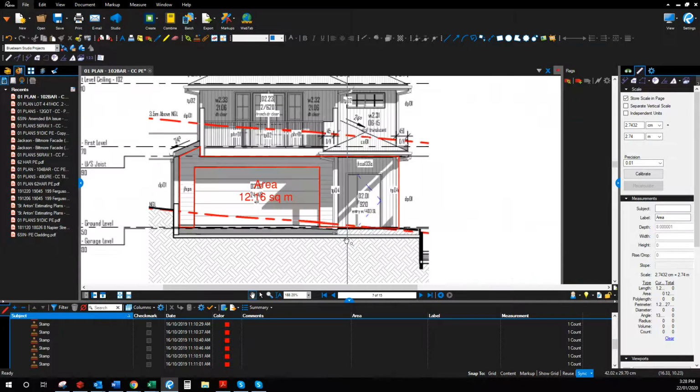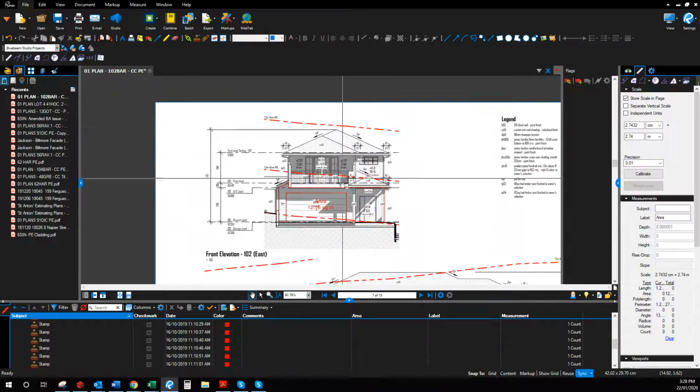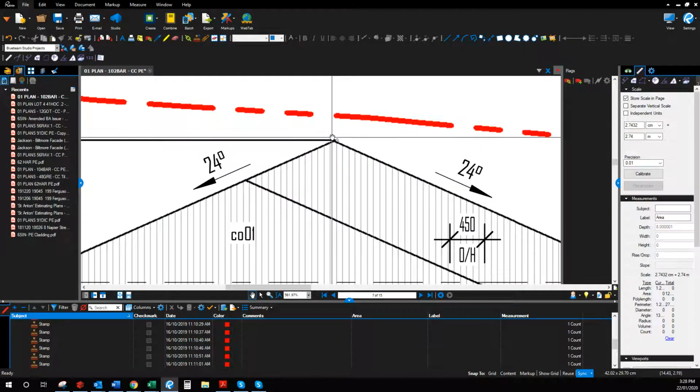Because in theory, if that line is really nice, and that ground level is perfect, the house shouldn't be higher than that. But then we also get a certificate at around framing stage. So when all the frames and trusses are up and the roof's getting close to being put up, they'll come and measure that top line, and they'll give us a certificate that states we haven't built higher than that. Okay, before we keep building any more.